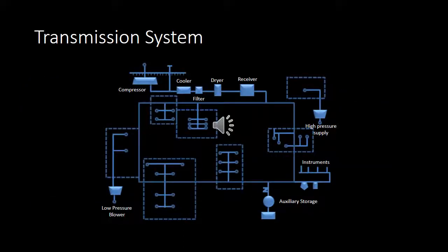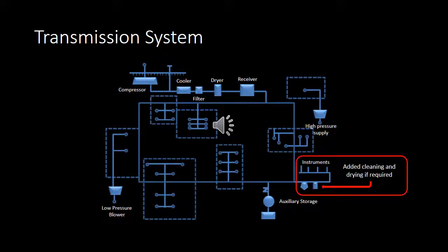A typical compressed air system includes distribution piping serving different departments or buildings. Small but critical loads needing special drying or filtration can be served efficiently off the main loop. An example is the instrument air system. This saves the added expense to dry and filter the whole plant air system for this small load.